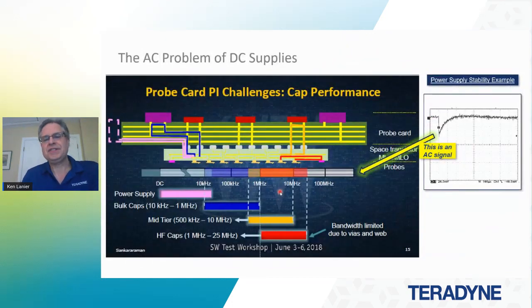The other thing that's interesting about these power supplies is we called them DC supplies in the beginning. We said, well, it goes from 0 to VDD, but as we're discussing, a lot happens between 0 and VDD. In this case, the pattern has not started, the pattern starts, and then the power supply, this is the VDD voltage, will eventually recover.